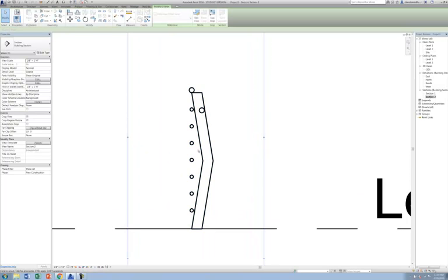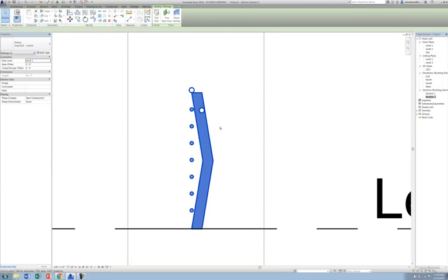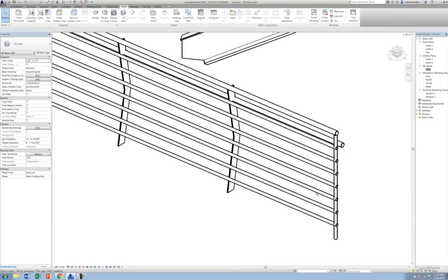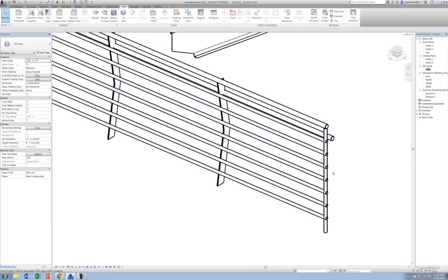So here you can see that profile gets loaded in as the height, and again that top rail is going to sit right on top of it, right on top of the baluster in terms of the reference, and the guardrail is sitting out here, and then our rail construction is made up of the rest of these parts. Something that you probably saw there in 3D is that the end baluster here stayed as a pipe condition.